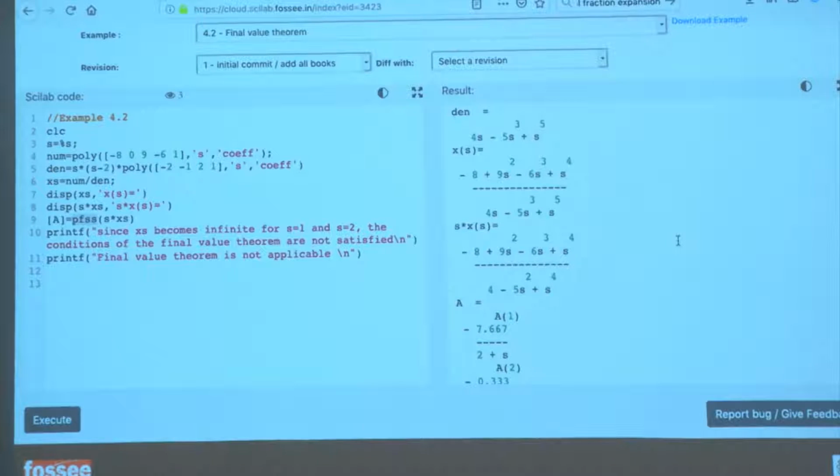Okay, I'm going to ask you a quiz now. Why is it displaying only the denominator? What happened to the numerator? Why is NUM not displayed? Why is DEN, something poly, displayed? There is a semicolon. Excellent, that's all. So let's remove the semicolon and run it. Now NUM has come, right?